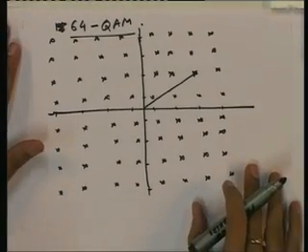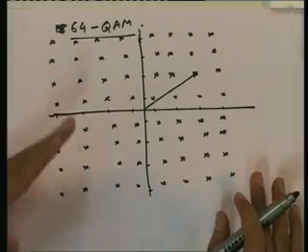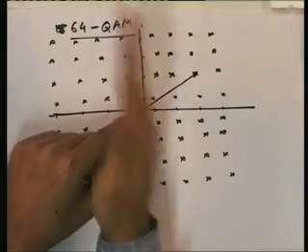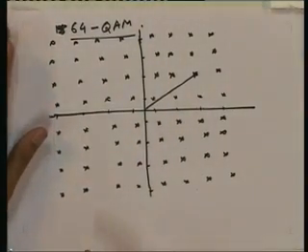Then we introduced another modulation technique called quadrature amplitude modulation. It is called quadrature amplitude modulation because we are doing combined amplitude modulation of two quadrature signals. One is cos, another is sine. There are two quadrature signals and we are doing combined amplitude modulation of both the signals. This modulation can also be viewed as joint amplitude and phase modulation of a single carrier signal. If you represent this in polar coordinates, then it becomes amplitude and phase. Every point has some amplitude and phase. So it is joint amplitude and phase modulation also.